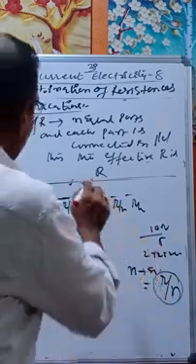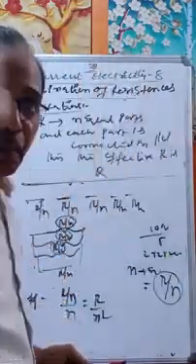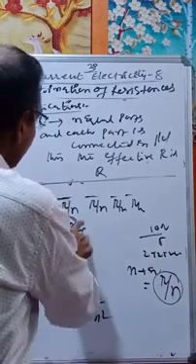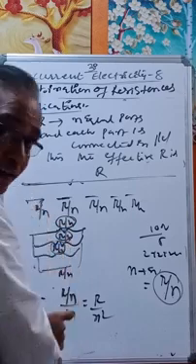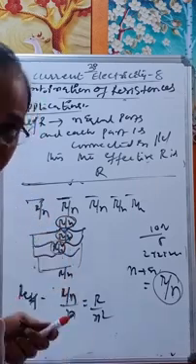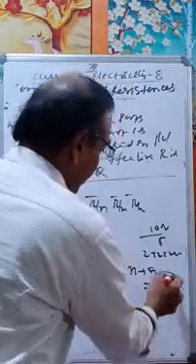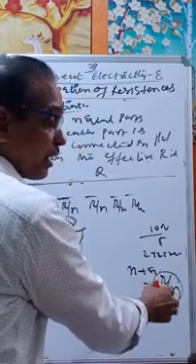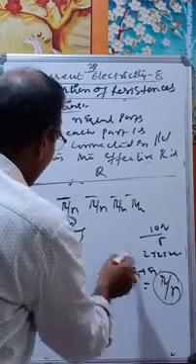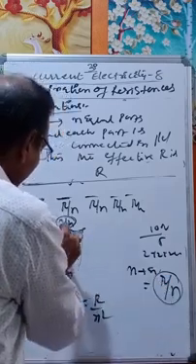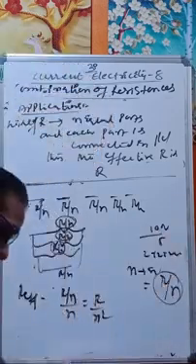I think you got this one. Here we have taken a wire. The resistance of the full wire is R. It is divided into n equal parts. Therefore each part has resistance R by n. Now each R by n is again connected in parallel. If n equal resistances R are connected in parallel, the effective is R by n, as we derived. Therefore, in place of R we get R by n. How many parts? n parts, so divided by n. Therefore, R by n square. This is one of the important applications.